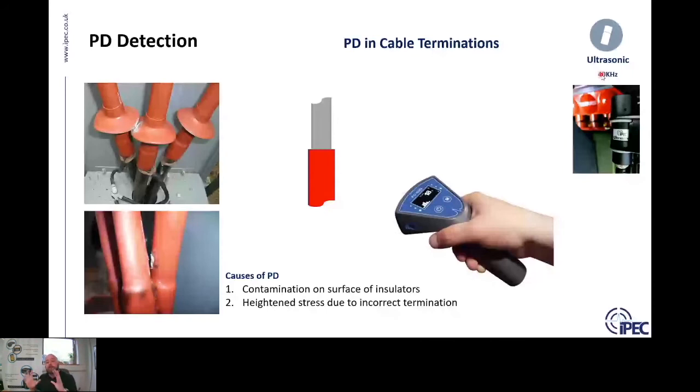While some switchgear is sealed and they can't always be applied, particularly for spot testing, for permanent monitoring we can install the sensors inside terminations. That's quite a common thing to do, like this sensor here. For portable handheld equipment, some switchgear is sealed. However, some switchgear has louvres or gaps in the panels where you can get audible or ultrasonic signals coming out. All we need to do is point our ultrasonic sensor in the direction of the HV point. The directional sensors have about a 30-degree window. If the PD is occurring, it will be detected by the handheld instrument.